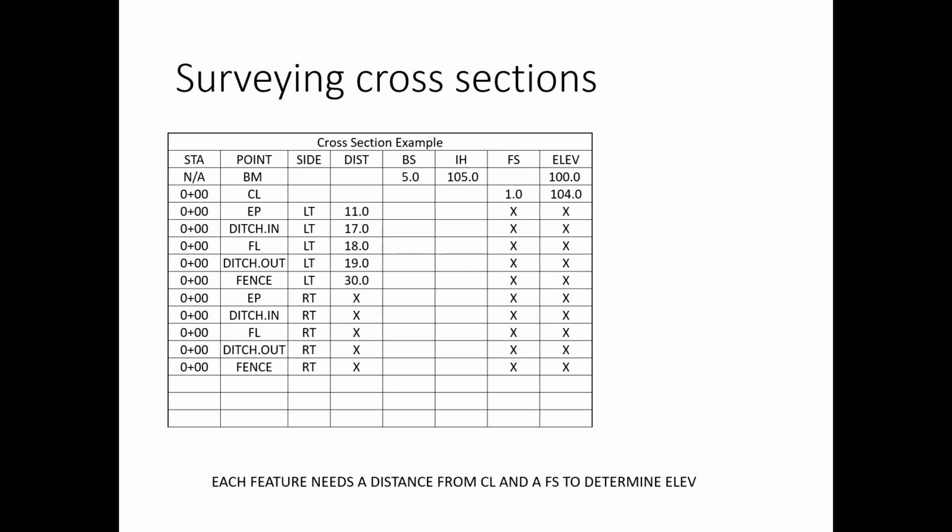like a manhole cover, any concrete, established feature that is not going to move. There's a very definite point, and then you can shoot that elevation as a foresight, establish the elevation, move your instrument, then again shoot the backside to reestablish the instrument height, and then just keep moving down the road.